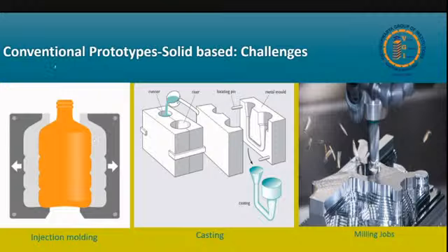There is a nozzle on the top, and it pushes molten material into the mold, and it takes the shape of the cavity. Then the mold cools down, and the mold pieces are switched apart so that the part can exit. So this is injection molding.